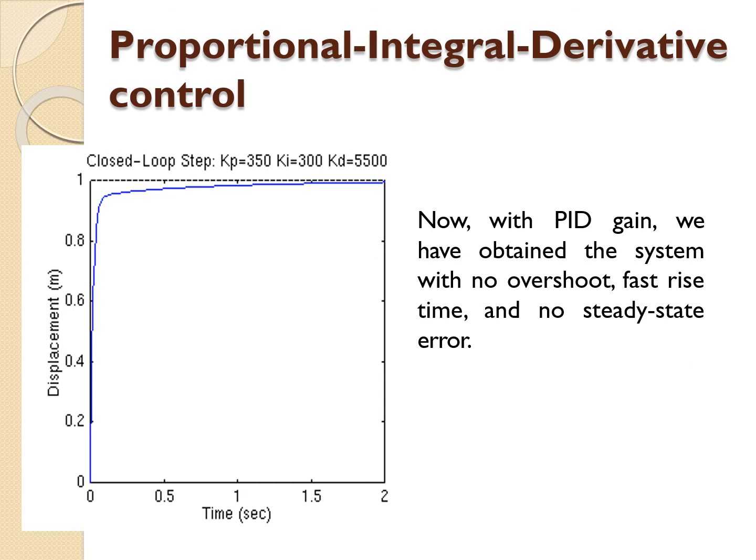Okay, so lastly, in order to eliminate 100% the overshoots, and to get the fast rise time, and to eliminate the steady state error, we can add in derivative control to the proportional integral control. So from this response, we can say that the rise time is fastest.